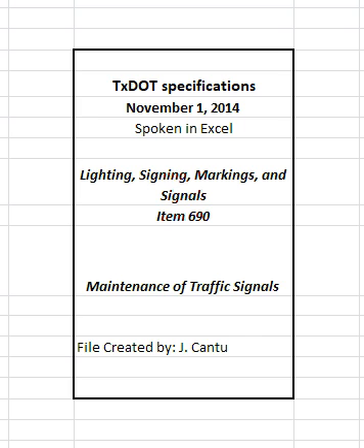Return unused or removed materials deemed salvageable by the engineer to the department upon completion of the work and before final payment at locations shown on the plans or as directed. Dispose of materials deemed unsalvageable by the engineer in accordance with federal, state, and local regulations. When materials are required to be furnished by the contractor, meet the materials article requirements of the pertinent item.